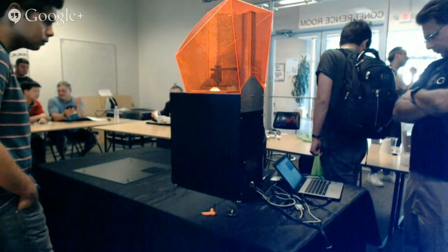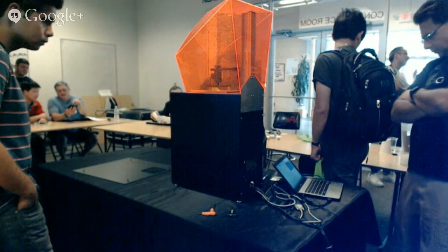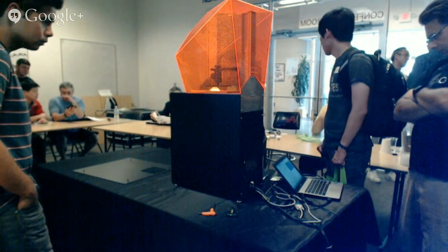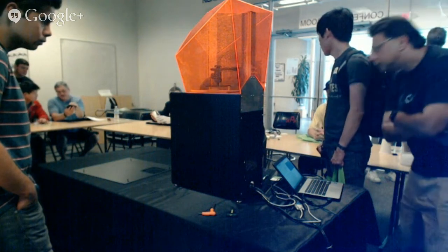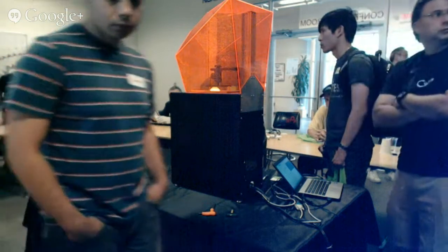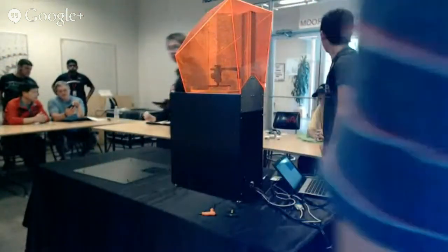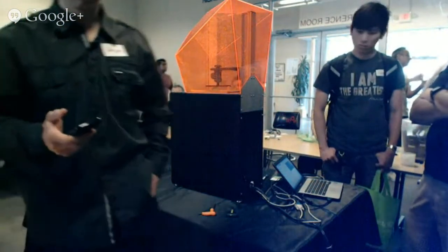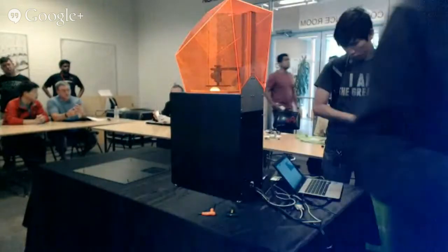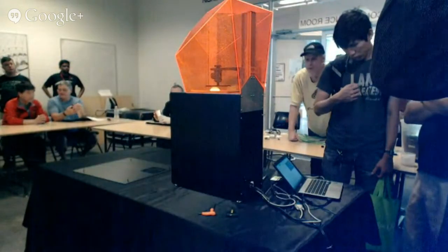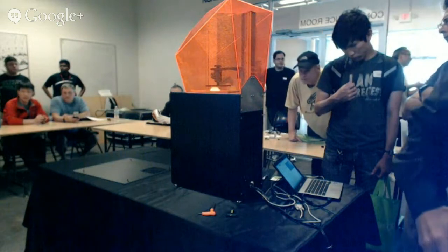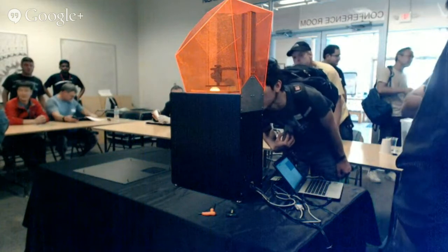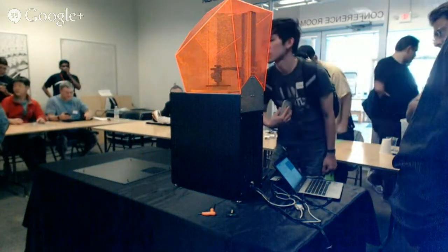That is part of the secret sauce that makes these vats way better than almost any other 3D printer out there, at least in my opinion as a user. Most 3D printers, if you got like a Form 1 or something, you don't print on this film. This is Teflon. You print on silicone. And silicone is less sticky than Teflon by a significant degree for 3D printing. Not because it's smoother, but because it adsorbs oxygen or air. So it holds molecules of air on its surface because its surface is not super smooth and super hard. And that supercharges the inhibition.